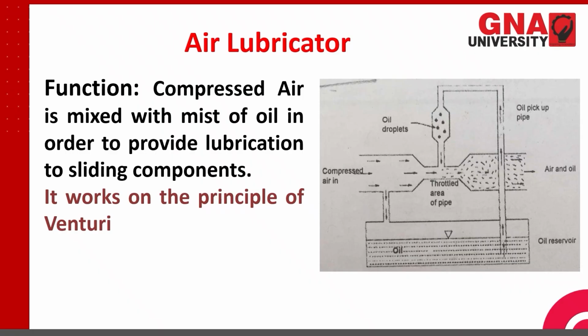Okay, so this poppet assembly is moved with the help of the movement of the diaphragm. As the diaphragm lifts up, it will move the poppet up and this passage will get open and the air goes out here at the pressure that is set with the help of the knob, which we can see on the dial gauge, showing which pressure has been set.